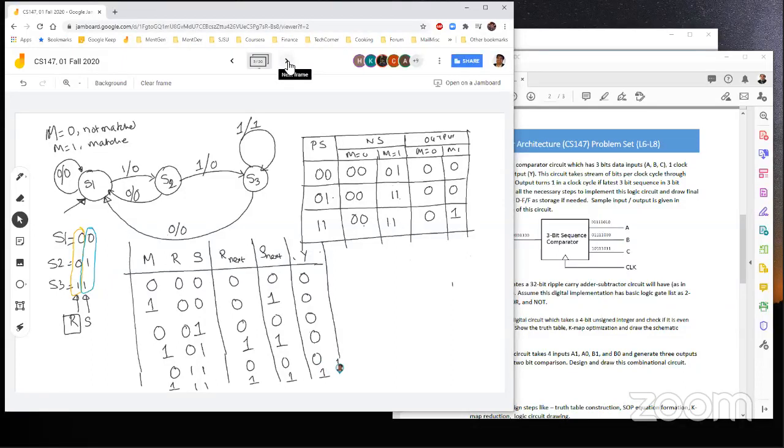So that becomes my truth table for the sequential machine. And then we can actually make equations there, right? Y equals sigma m of, okay, what is this m? Let's determine this value. This is m0. This is m4.